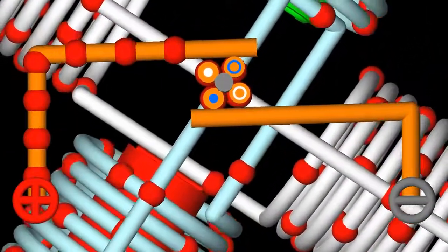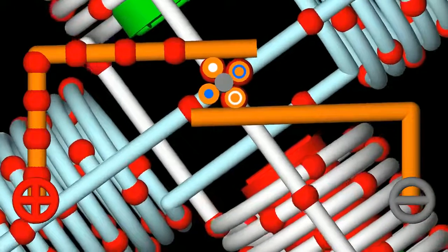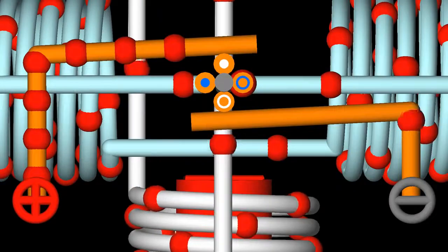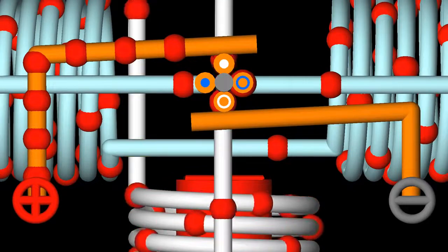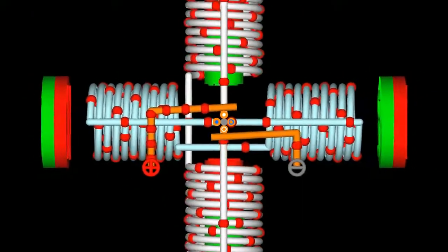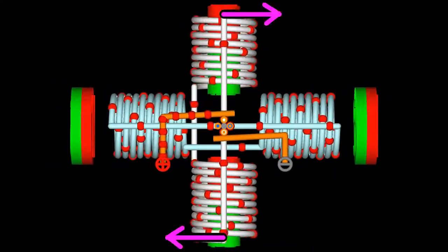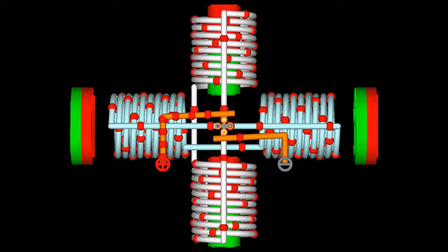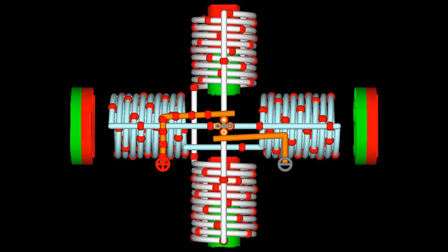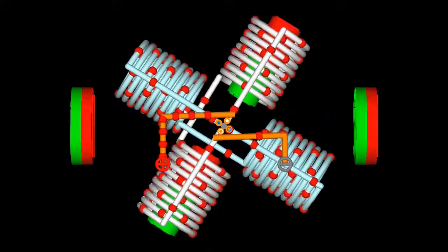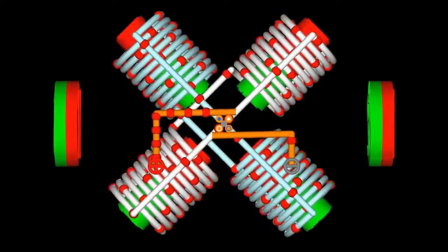Let's define the position with the white marked electromagnets at the vertical position and with the dot marked end at the top as initial state of rotation. That electromagnet is connected to the supply voltage, resulting in a magnetic field being produced. The magnetic north pole is at the top of the arrangement, thus the resulting torque points clockwise. The light blue electromagnet is not connected to the voltage source, thus it has no magnetic field. Consequently, the motor spins clockwise.